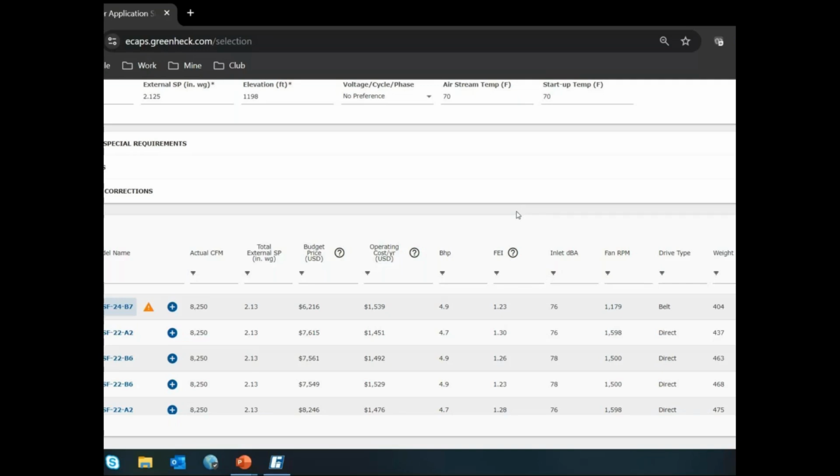180 degrees is my line, right? If I'm moving greater than 180 Fahrenheit, I have to start looking at different construction. A spun aluminum may not be the right one at that point. If I'm moving ambient air from a building, it's 70-degree air, that's perfect. Over the top of a restaurant exhaust hood system, that's typically in the 100s. Those spun aluminums work really well upblast for restaurant exhaust.